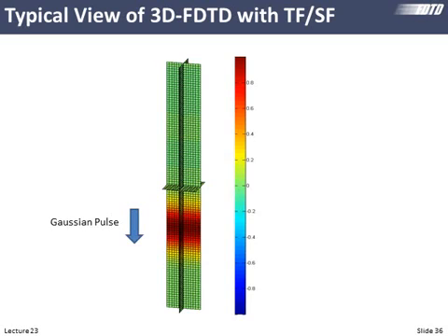So if we're looking at a 3-dimensional finite difference time domain model using this slice command, notice I'll take a slice through the middle of the field array and visualize it. And here's another slice that we're seeing mostly in this view. And then also a slice through the middle. We can see our pulse source, if you will, but in 3 dimensions now. So this is a pretty typical view of what you would see in MATLAB running a 3-dimensional finite difference time domain code.